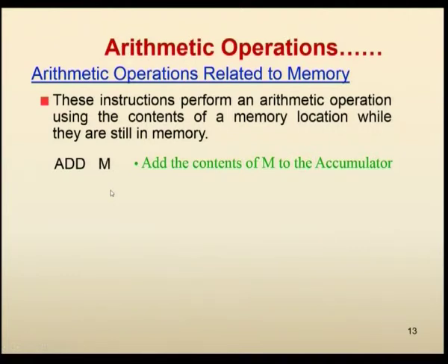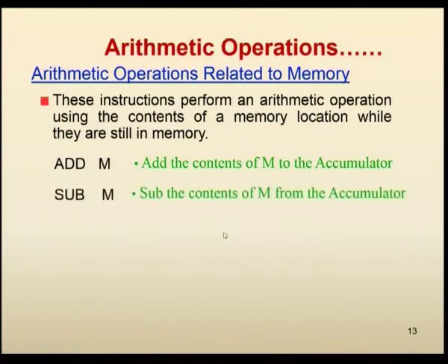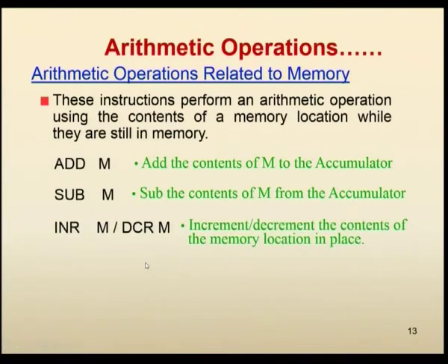The memory location will be the location pointed to by the HL register pair. So, you have to preload the memory location into the HL register pair. From the location pointed to by the HL register pair, the data stored in that location will be taken and added to the contents of the accumulator, and of course the result will be stored in the accumulator.